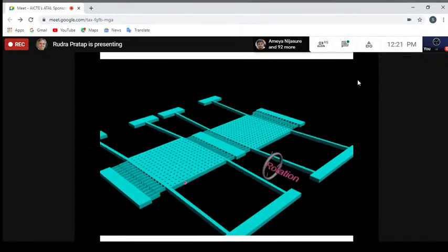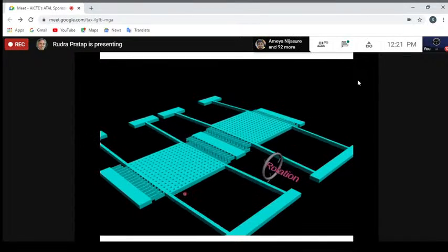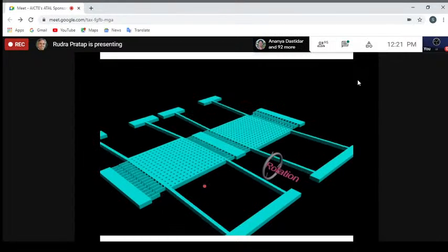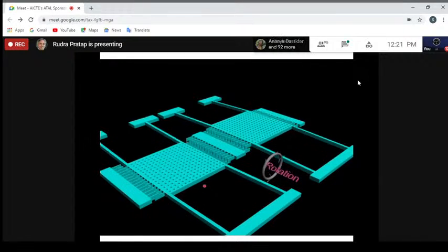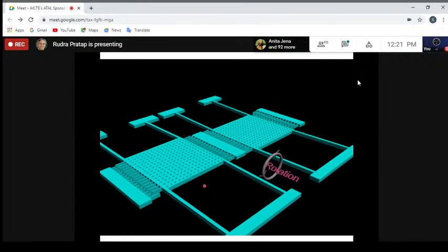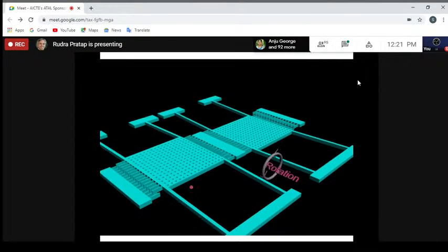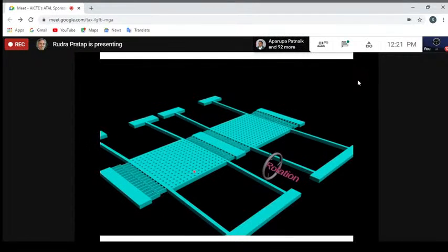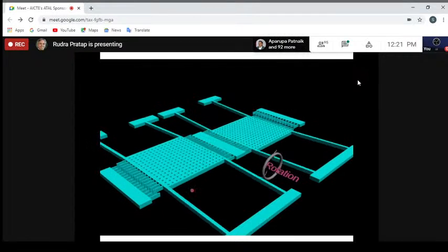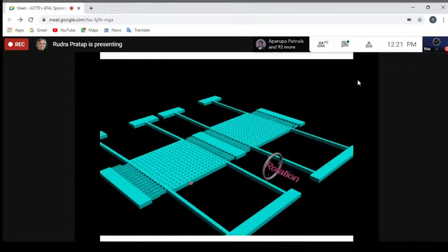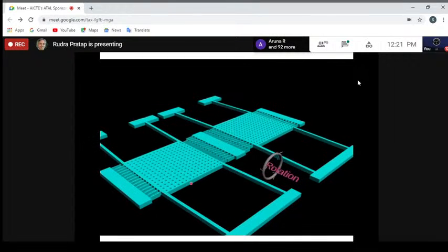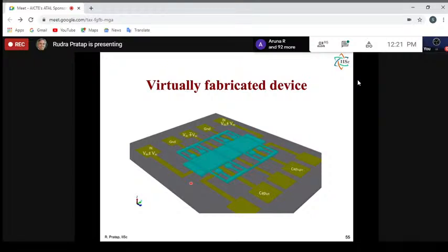If it is going up and down, and I have another electrode at the bottom of this plate, then I can use these two as parallel plate capacitors, and the capacitance changes, which is indicative of how much the rotation is. If I can get that change in capacitance, from which I can figure out the amplitude of this vertical motion, then by back calculation I can figure out what omega is, my rate of rotation. And that's what gyroscopes are for.